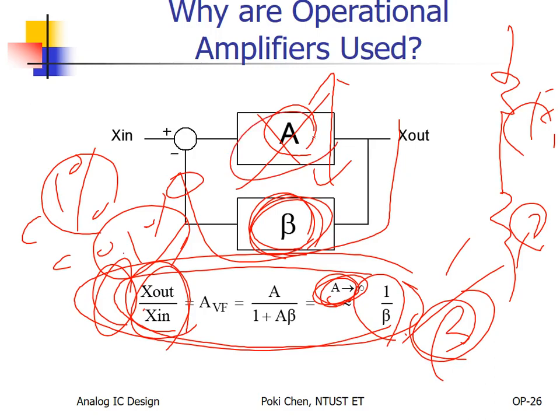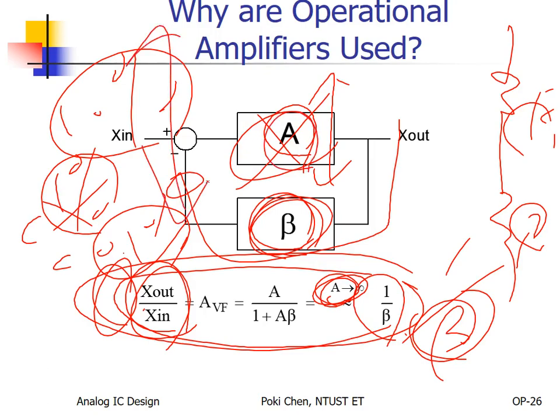But how about the open-loop gain? Never mention 1%, never mention 10%. I promise you, usually 20 to 30% variation, and you have no way to control it. Or even, the larger the gain, the more variance. Sometimes maybe even 50%, 200%, 300%.